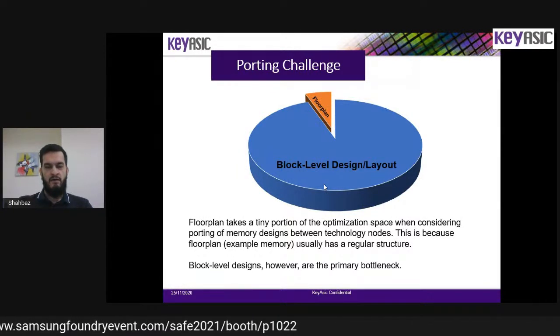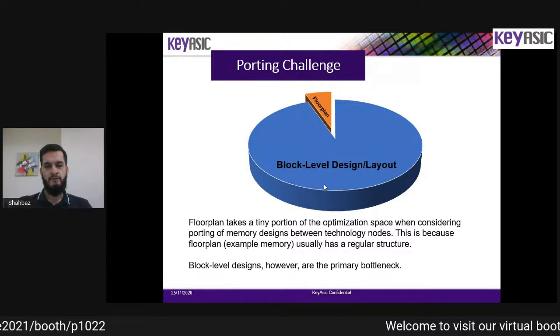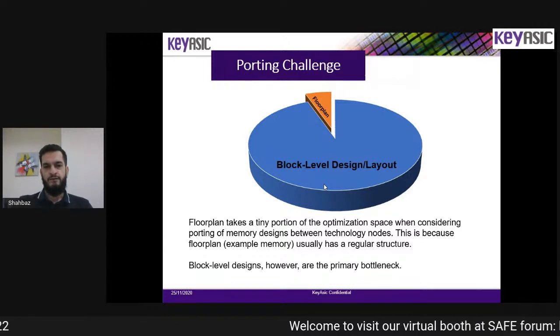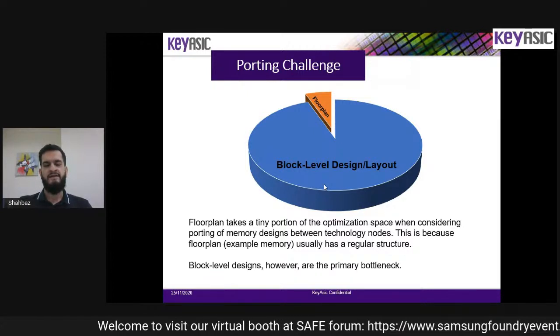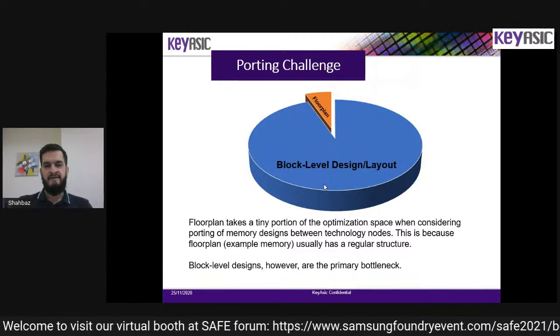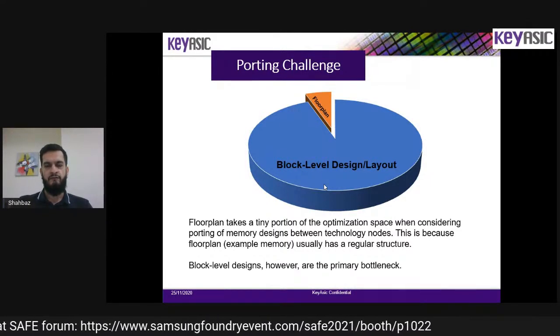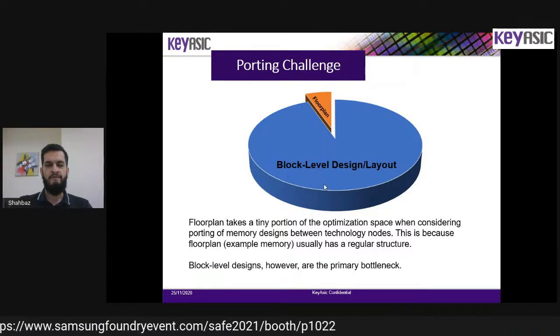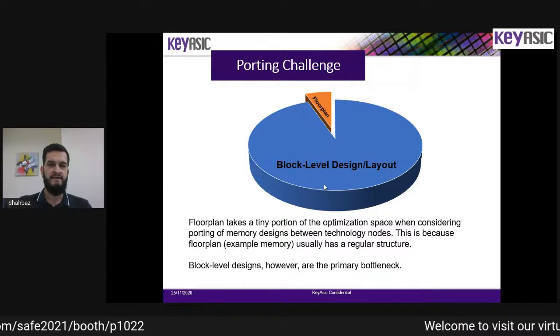So our aim for this memory compiler and our plan to build this framework is to build block level compilers that would generate the block level cells, designs, and layouts and optimize them automatically, with the minimum amount of effort required. And like I already mentioned, it should be able to accept templates for these cells.